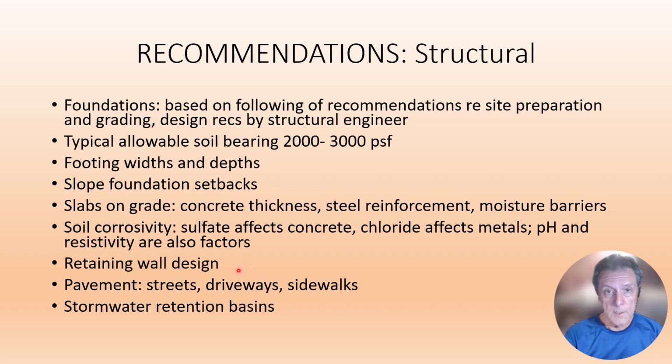You want to give some recommendations for retaining wall design, for the footings, for the heights of walls, for the distance of walls from property lines and so forth. You want to discuss and give recommendations for streets, driveways, and sidewalks, and the preparation of subgrade for those pavements. And importantly, a lot of sites will require stormwater retention basins, so that's something else you can give recommendations for.